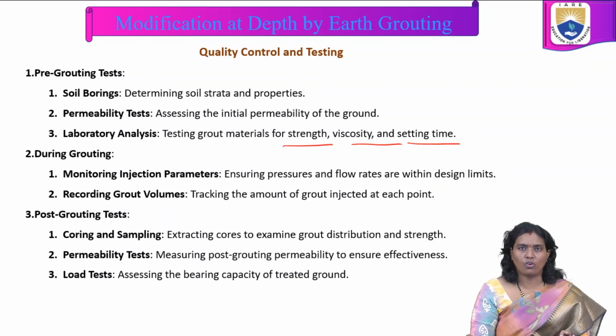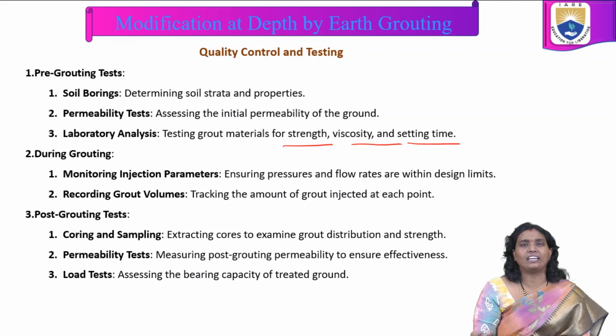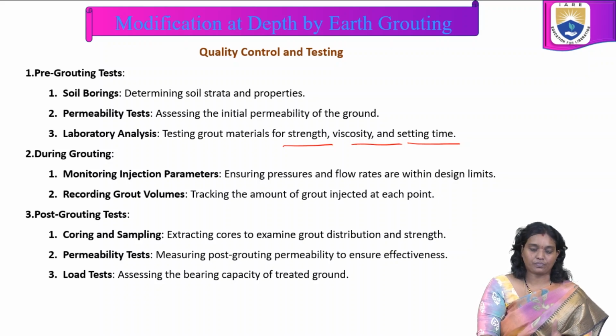So, pre-grouting, during grouting, next. Pre-grouting, we have to understand the soil parameters. During the grouting, we have to understand the processes, the flow rates and whatever the pressures, ensuring they are within the limits, and we have to understand each and every point of the grouting process.